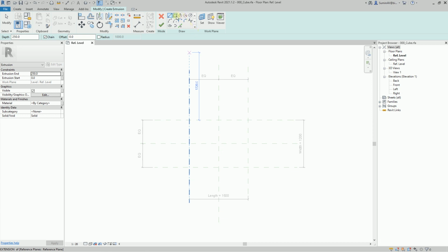Let's select it and attach it to the point of intersection of 2 reference planes. Then, going diagonally to the point of intersection of the 2 opposite reference planes, and thus complete the creation of a rectangle. Lock icons will come up. These locks need to be closed in order to establish a link between the reference planes, which serve as basis for our sketch, and the lines of the sketch. Without such a link, the sketch will be separate from the reference planes.